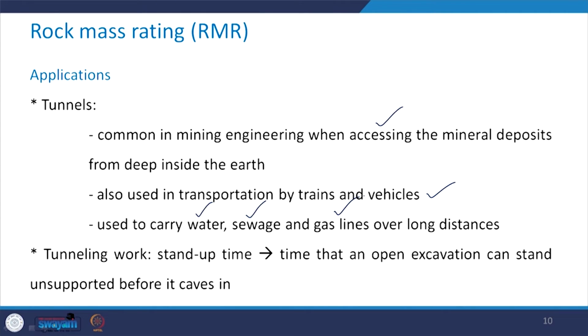Once you have made the excavation, one needs to provide the support system. That support system can be in the form of lining, shotcrete or rock bolts. So, the stand up time defines the time that the excavation can withstand unsupported without caving in.